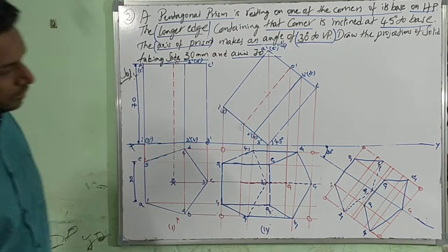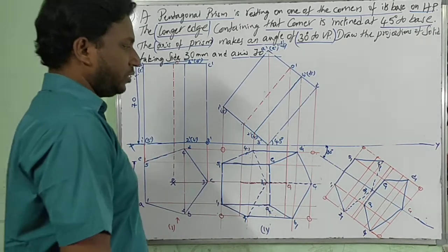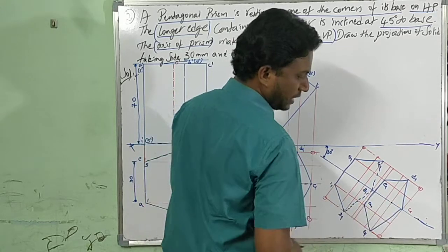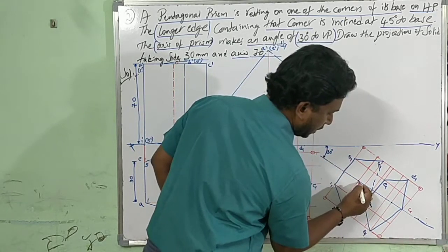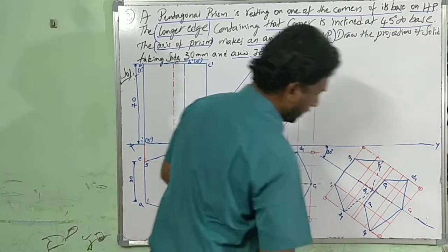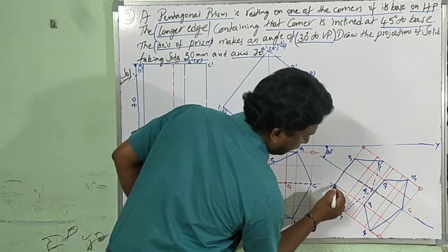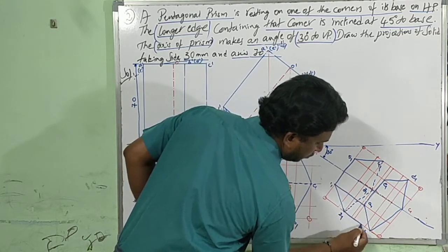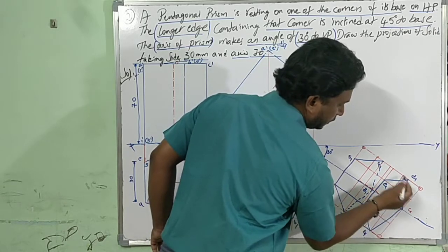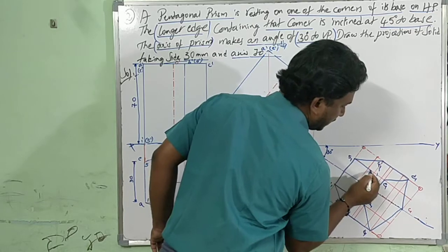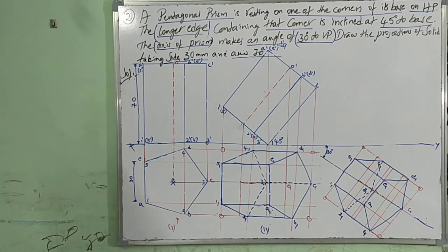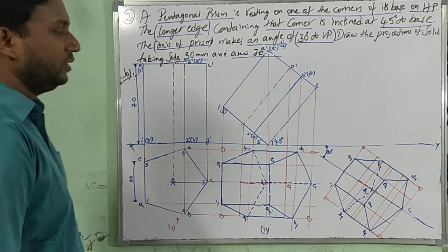See, I have drawn just the same thing by rotating. Now see the axis points also, from here to here it comes as axis. You can draw here dash-dot, to avoid confusion. Thick edges: A1, 1, 1 thick edge; B1, 2, 1 thick edge; C1, 3, 1 it's hidden; D1, 4, 1 thick edge; 5, 1 even thick edge. Just reconstructed that with respect to the center line at an angle of 30 degrees.